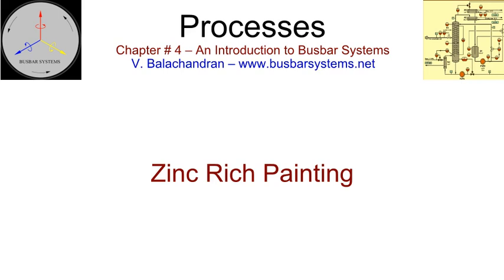While the application does cover the exposed surface, thereby providing protection, it is more effective as a provider of cathodic protection. It is an accepted practice to apply zinc-rich primer on the steel surface that is exposed and subsequently to give an impervious overcoat of epoxy paint over it. The total thickness of the combined application of the zinc-rich primer and epoxy paint can be quite significant, in the order of 150 microns. The thickness of the coat can be increased by multiple applications.